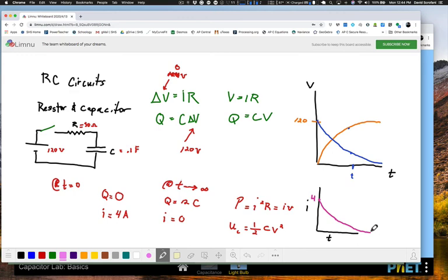All right. Now, there's actually a time factor. It's called the time constant. It's usually labeled tau for these circuits. Tau. It's equal to R times C. This is the time constant for this circuit. And it ends up being literally that, the product of the resistance and the capacitance. And you can calculate it in this case because you know both of these things, right? It's 3 for our circuit. 3 seconds, in fact.